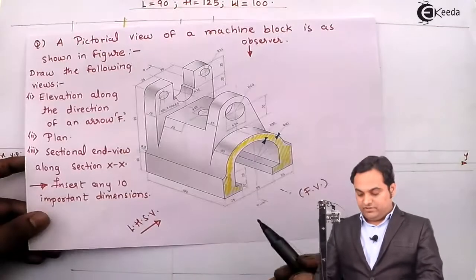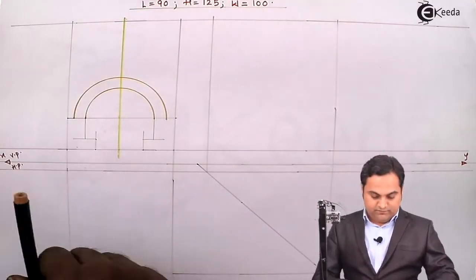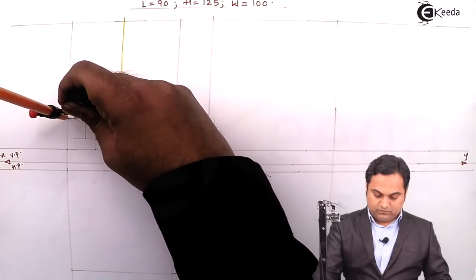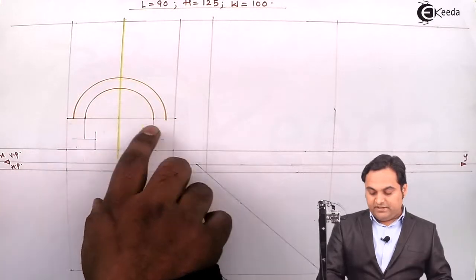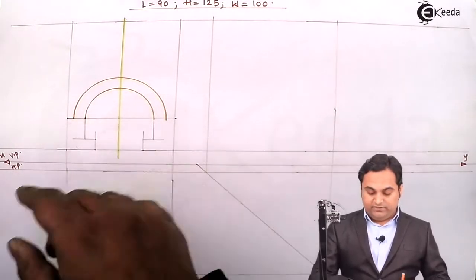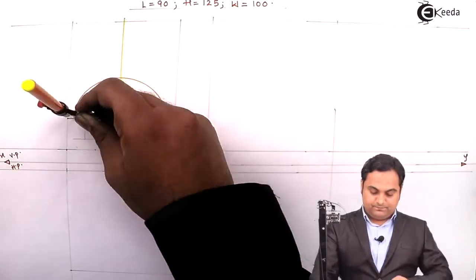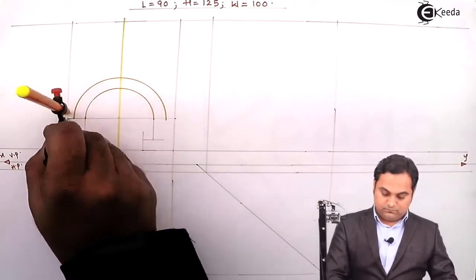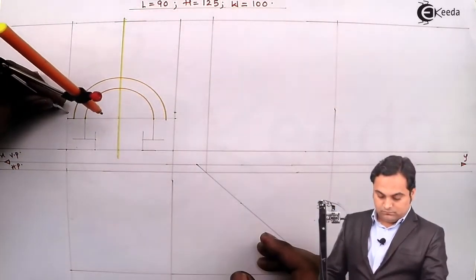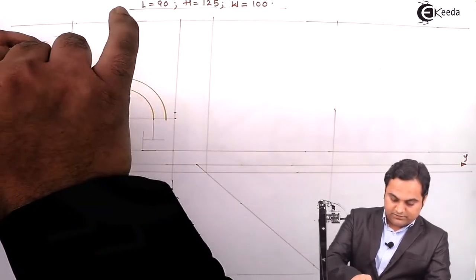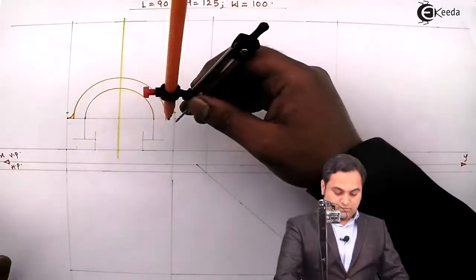Next, after that, if we see here there is radius 5 mm for this groove, or we can say it is a curve. So measuring this distance, and it has to be 5 mm because here the diameter is 80 and total length is 90. So leaving 5 mm. So for that, I'll measure the distance here. Keeping this center, joining it up to the curve.